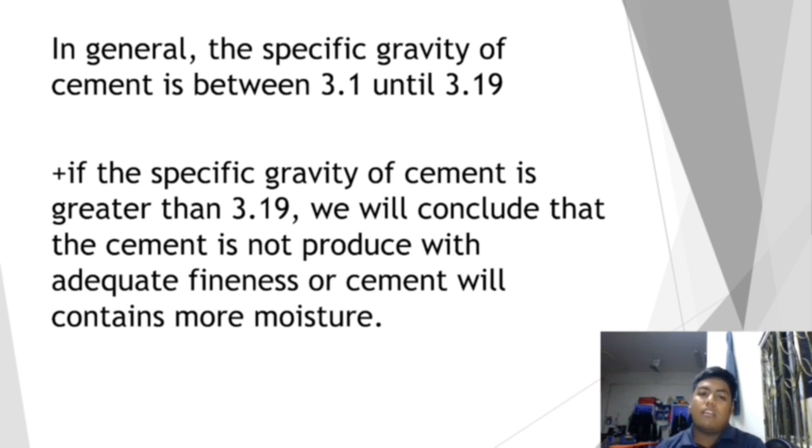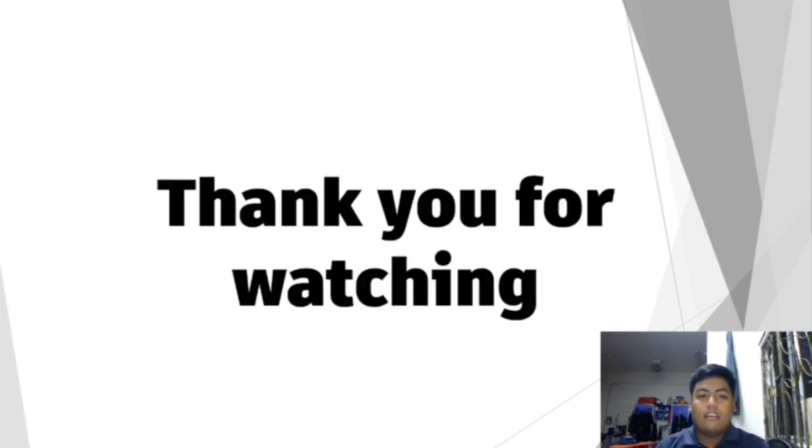If the specific gravity of the cement is greater than 3.19, we will conclude that the cement is not produced with adequate fineness, or the cement contains more moisture. That's all for me. Thank you for watching.